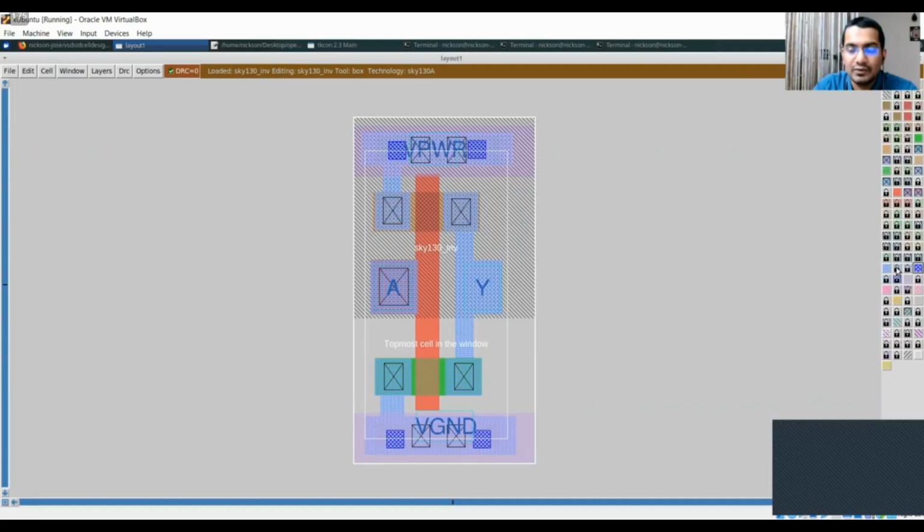Before we make that contact, we have to make a contact for, for example, the PMOS. The PMOS is actually inside a well, the dashed line inside the well. There needs to be a contact between the N well and the LICON. That is this. As you can see, that is more clear in the web page.